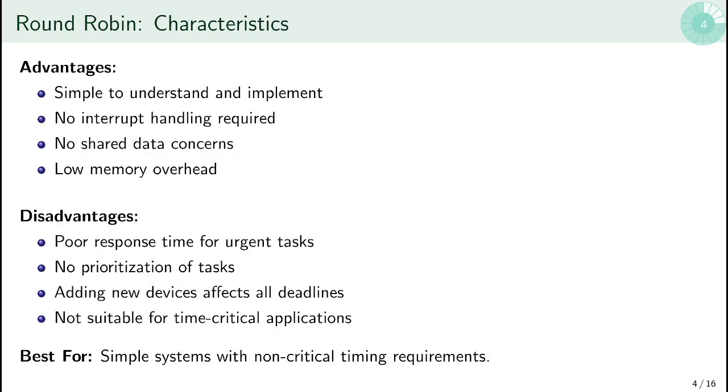So here are its advantages. It's simple, no interrupts, minimal memory, but its disadvantages are it's slow for urgent tasks, no prioritization of tasks, adding devices can break timings. It's not suitable for time critical applications. It's best for simple systems with non-critical timing requirements.